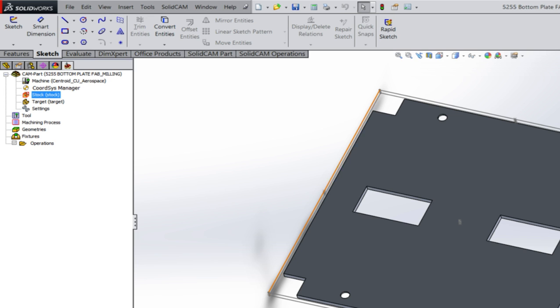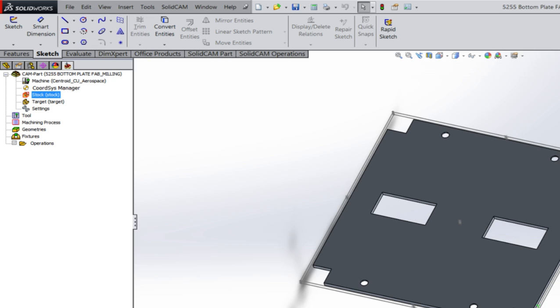So the problem with the outside is I can't cut all the way around here because I've got to hold this down. I'm going to have clamps in here, right? If you want to be efficient, what I like to do, remember I am going to use a little drill bit as a pointer to set my zeros. So I've already got a drill bit in the machine, right? Maybe I go ahead and drill these holes first. So if this were me, I would probably have clamps in the corners, 4 clamps in the corners right here.